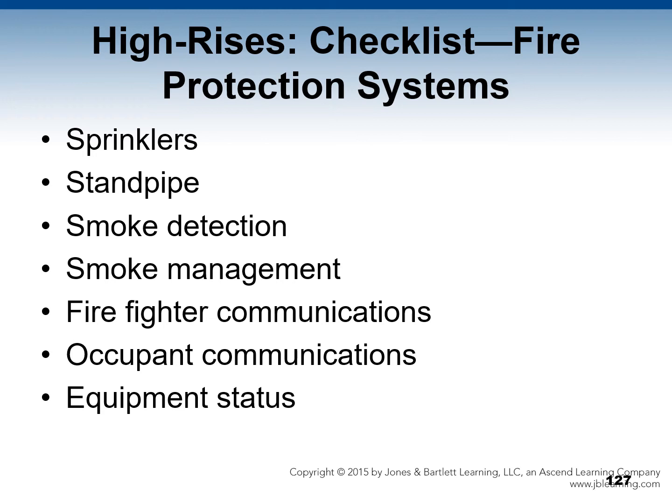And then, of course, firefighter communications. What kind of firefighter communication system does this high-rise building have? And occupant communications. Which type of communications are possible with building occupants? Can this system be controlled by floor or floors? And then equipment status. What are the indicators for fire pump, generator, and elevators? How are these pieces of equipment controlled from the command center?